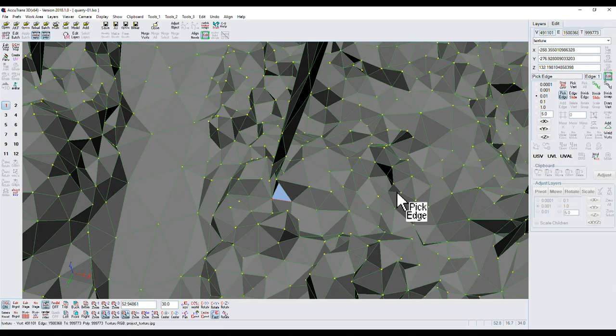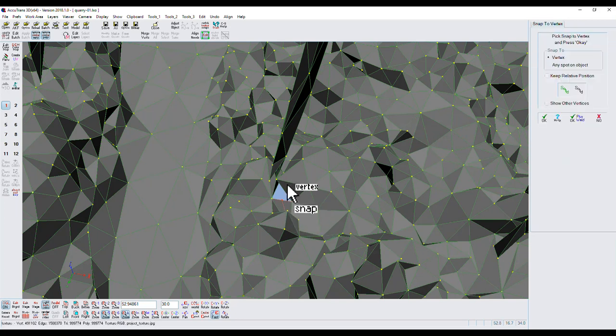So I can cancel out all the changes I made in here, except for adding triangles. And now that I've got that selected, I'm going to go to Divide Snap, and the edge will divide, and a new edge appears in here. And then I'm just going to go up and click on this vertex and try again.